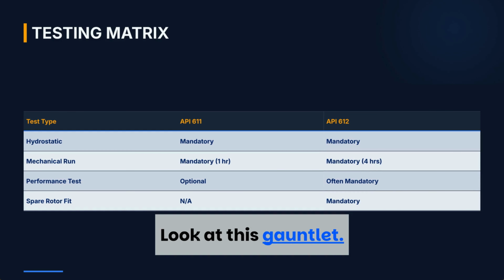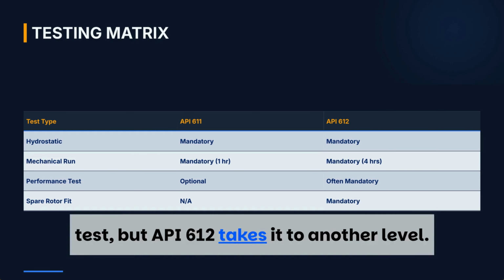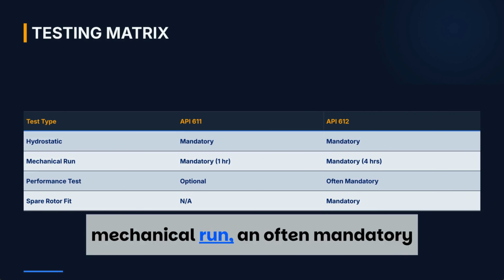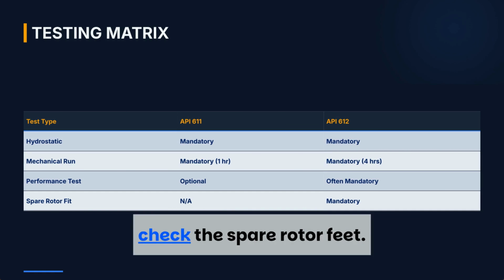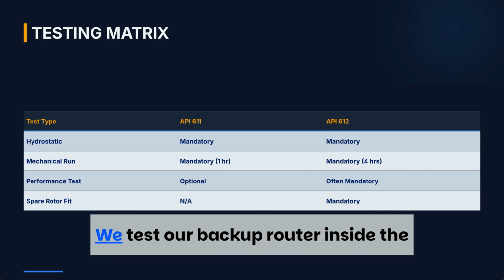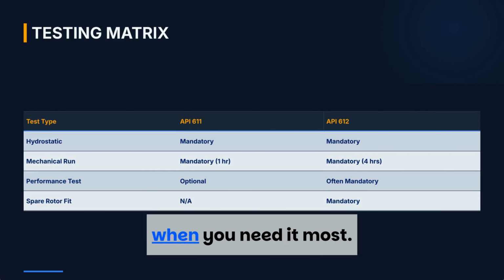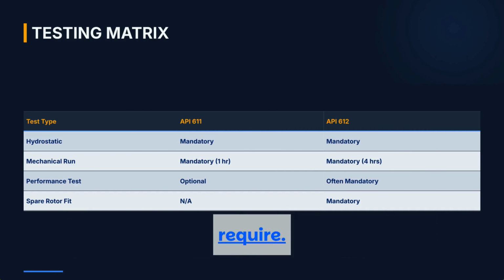Look at this gauntlet. Both standards require a hydrostatic test, but API 612 takes it to another level. We are talking about a 4 hour mechanical run, an often mandatory performance test, and the ultimate fit check, the spare rotor test. We test our backup rotor inside the machine before it ships to ensure it works when you need it most. API 611 doesn't even have a spare rotor test requirement.